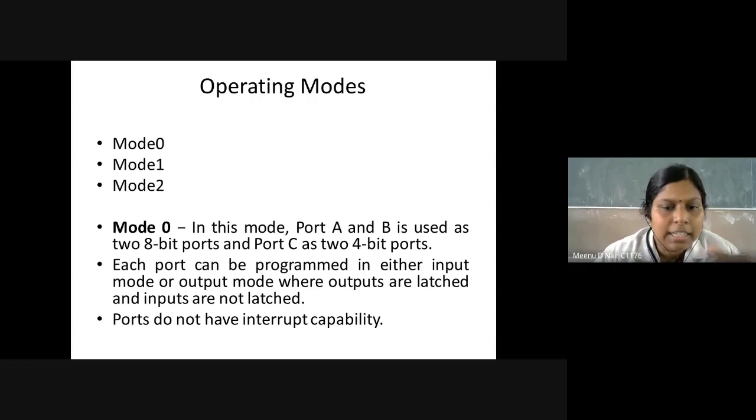And it doesn't have interrupt capability. Only when the microprocessor accepts will it send the data. It doesn't interrupt the processor. So that is the mode 0 operation.